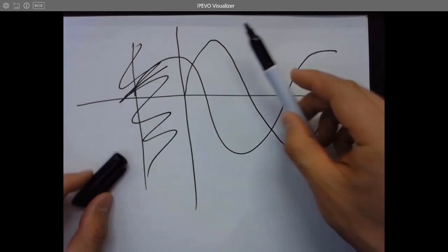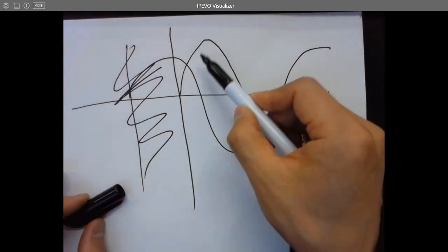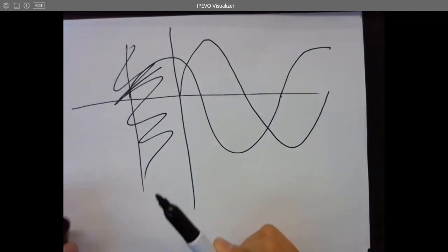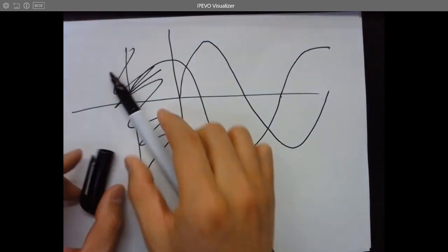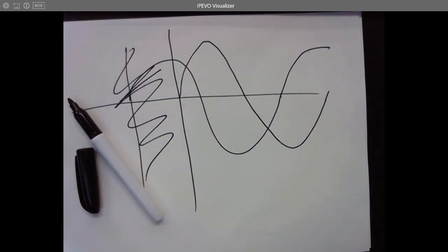By simply changing the amplitude of either one or both of them, doesn't matter. Which means by simply changing the amplitude of these two signals, which have a 90-degree phase shift, the phase and amplitude of the generated third signal can be changed, right?